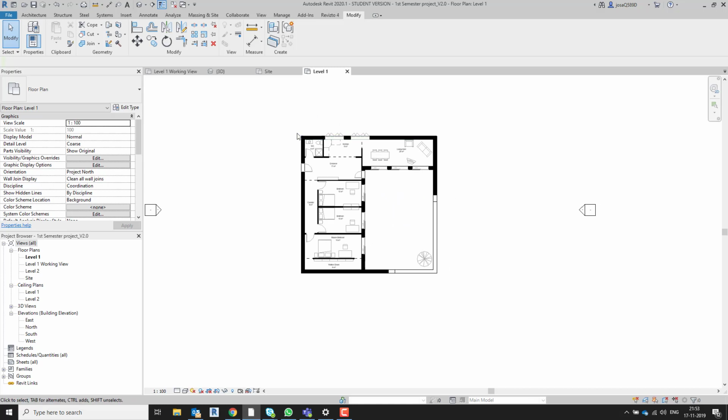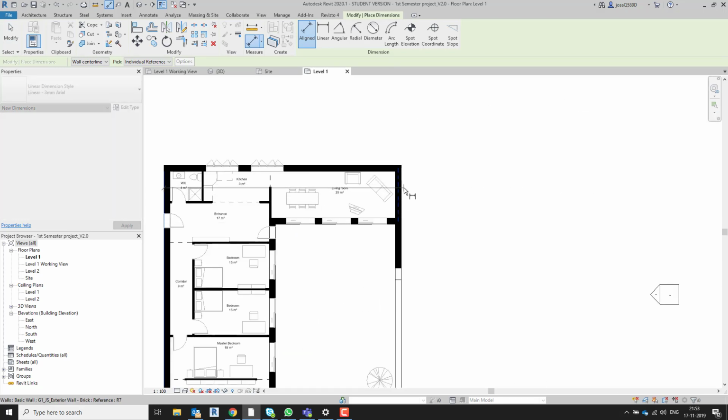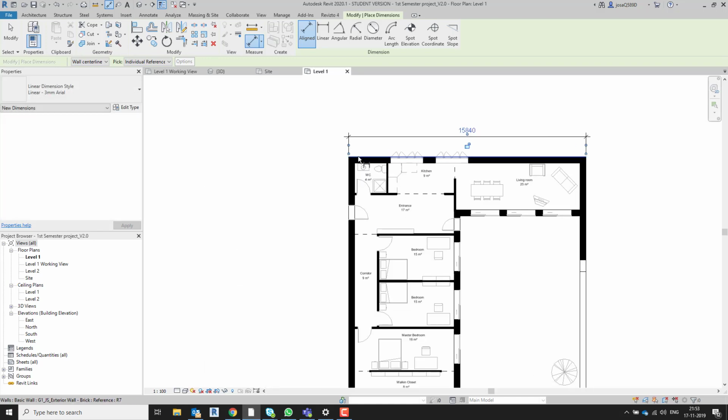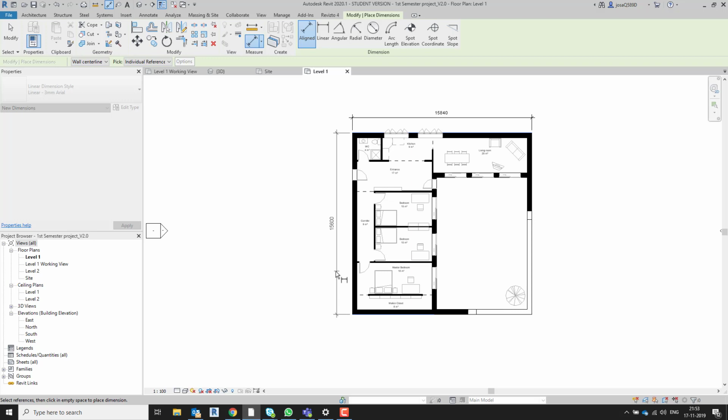I'm gonna have some overall dimensions, so my client knows what size is the house, and what their overall dimensions are. So I'm gonna come from here. I'm gonna go from this face to the other edge, 1580. Again here, try to keep the same spacing, more or less. Tab for the edge, and tab again, so my client knows how much.